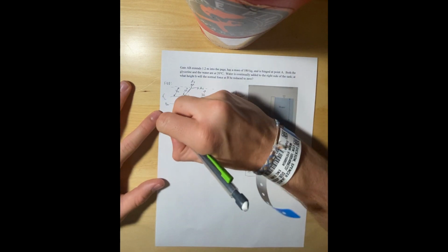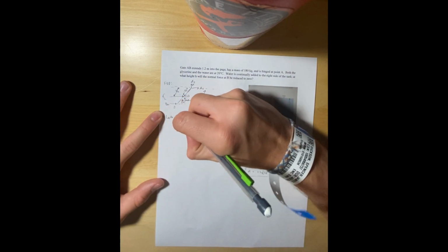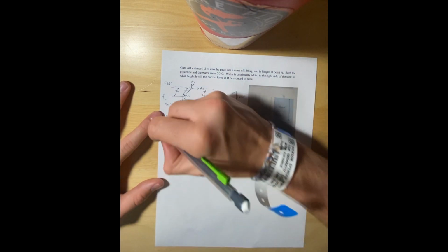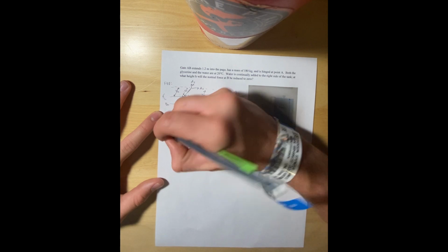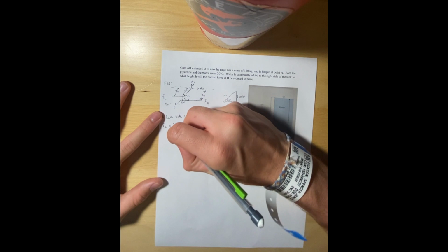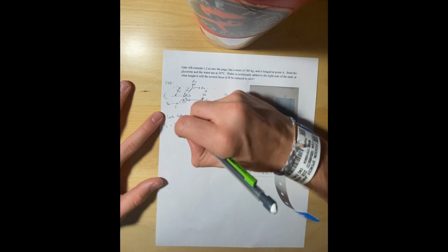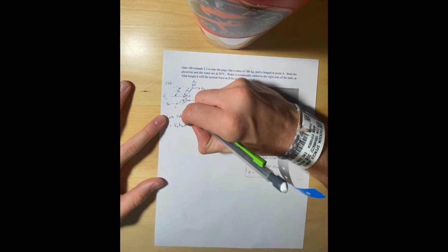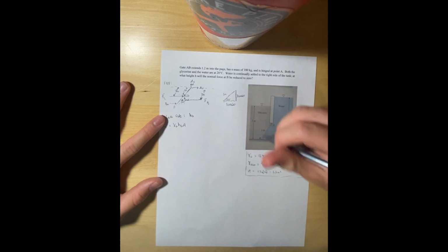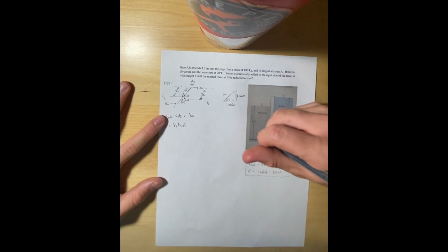On the left side here, we're going to need force L is equal to the specific weight times the height, h sub g, which we're going to solve for real quick, times the area. And so the height, the h sub g term, is going to be this 2 meters right here minus, so this looks like this is where it's acting.